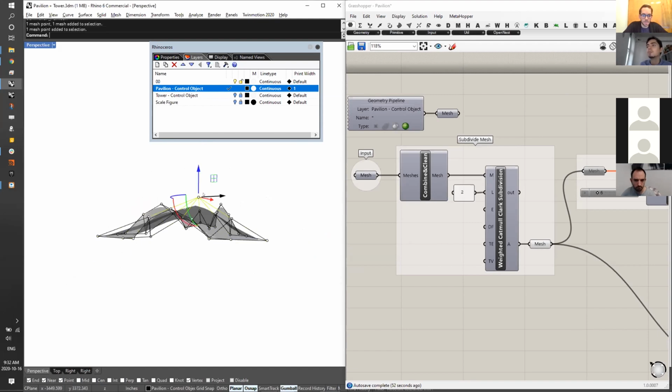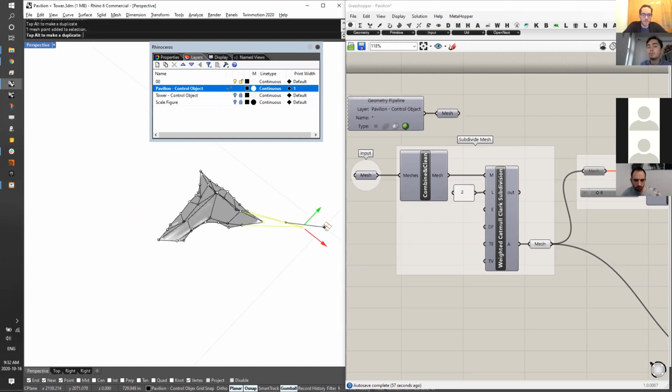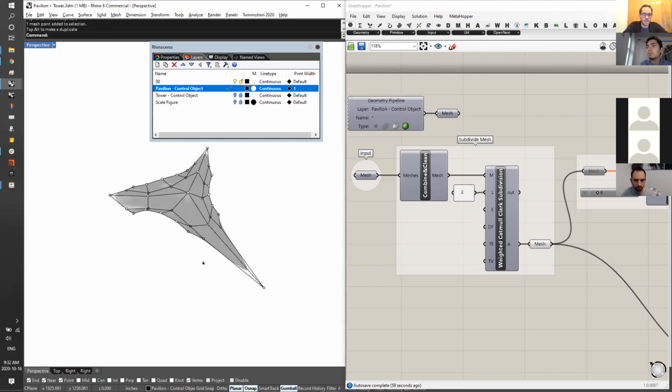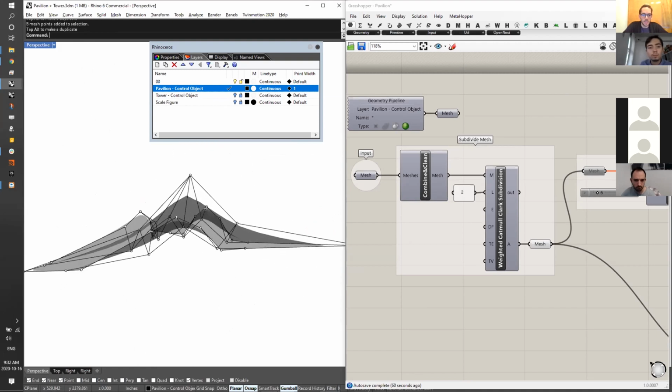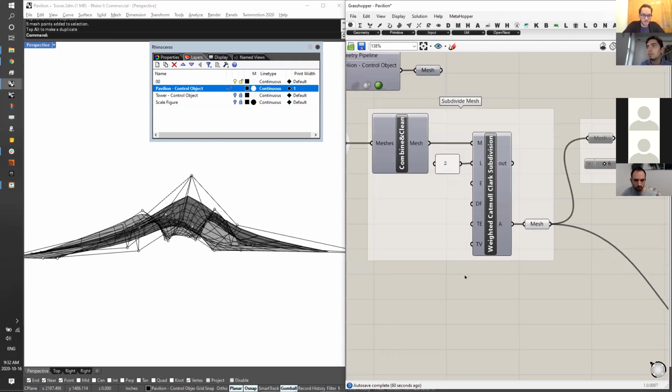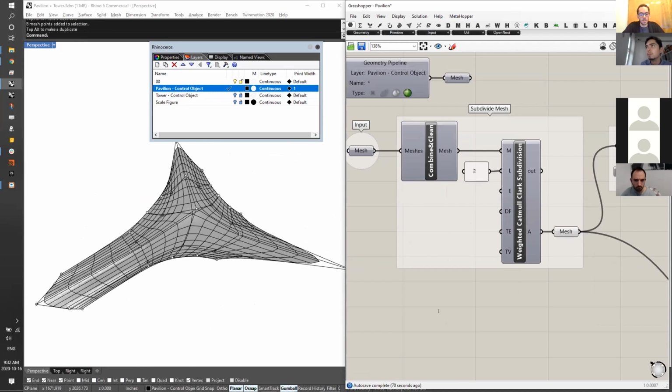As you may know, we can start to manipulate it and do funny things with it. We can have it do strange things and have it sort of move around. Let's say you have a particular site that needs a particular set of conditions. You can start to edit those particular constructs and then have it fine-tuned to that, which is very, very useful. And also, to turn on the edges in Grasshopper, if you don't already know, it is Control plus M. And if you just do that, you can turn the edges of your meshes on and off, which is very useful for when you're doing this kind of work.